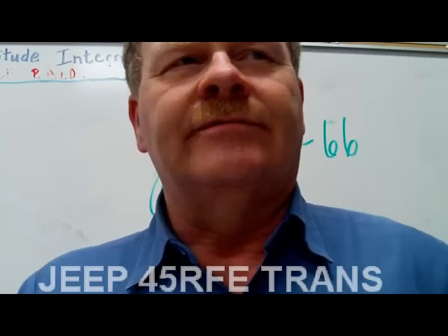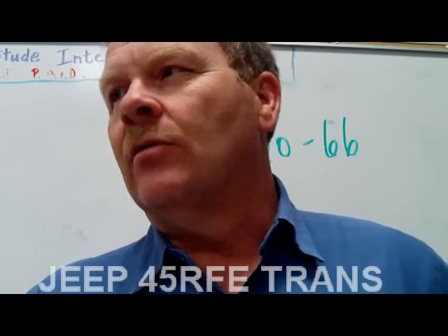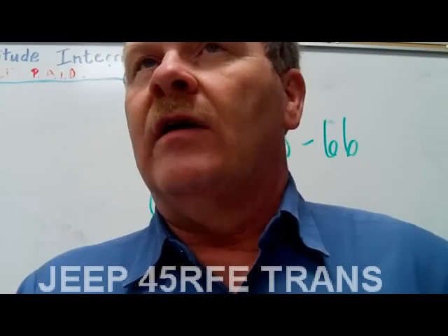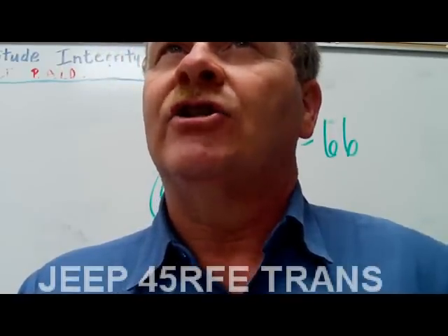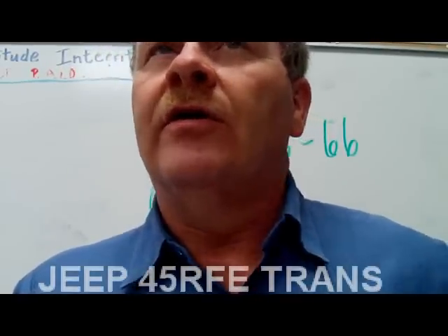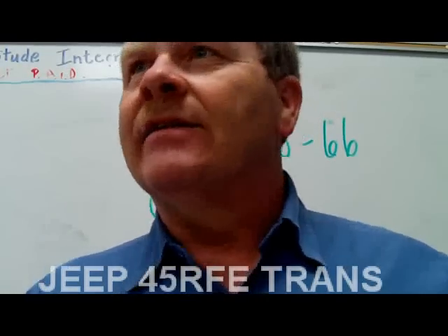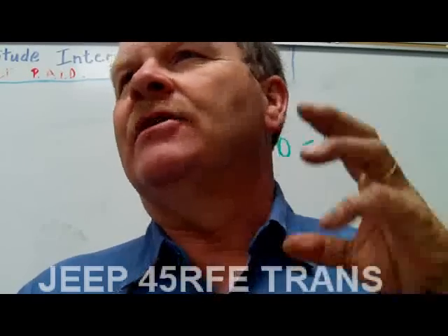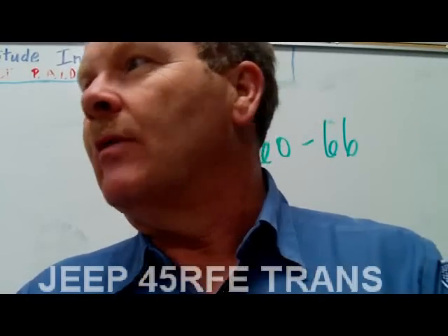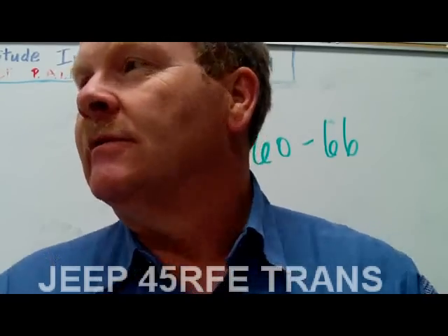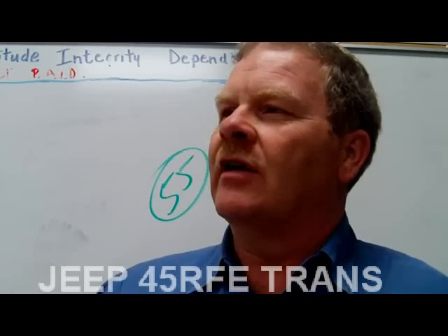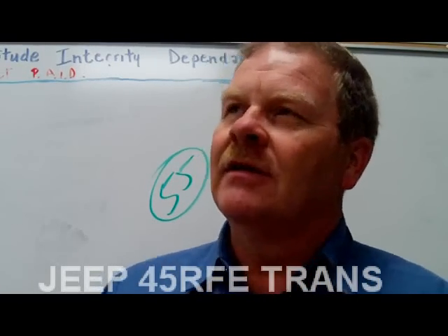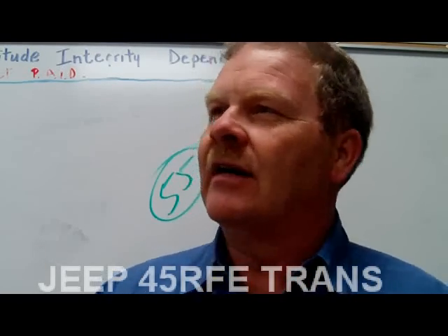The original version of that thing came out in '79. It was an AOD, automatic overdrive. The way it locked the engine all the way through to the rear wheels, it had a shaft that was hard connected to the torque converter that went down inside the transmission. Whenever a band applied in there, third gear would give you the straight lock up all the way through, and then fourth gear would engage the planetary that would give you a faster output than input.